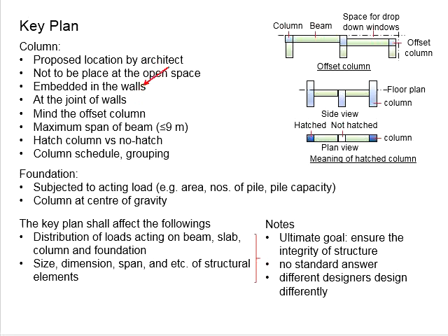You can embed the columns in the walls. Make sure that they don't stand out from the wall surface.